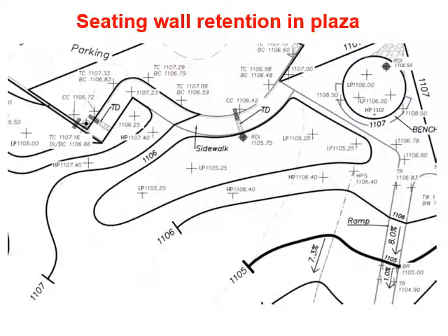So if we look at the spot elevations, we have a similar sort of thing. Obviously, there's no curb cut here because water is simply sheet flowing into the system from both sides. In terms of spot elevations, we're going to have the low points that are in the system. We're going to have a high point that is related to the bench. We're going to have the top of the bench itself. And of course, we're going to have the raised drop inlet. And the raised drop inlet, again, needs to be lower than the high point.